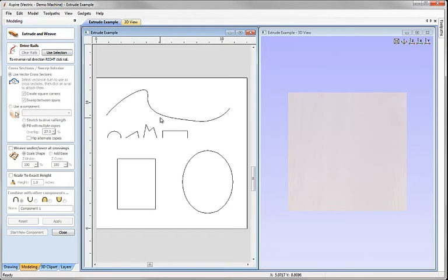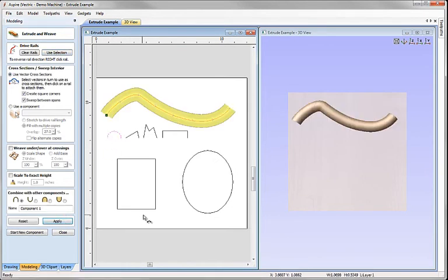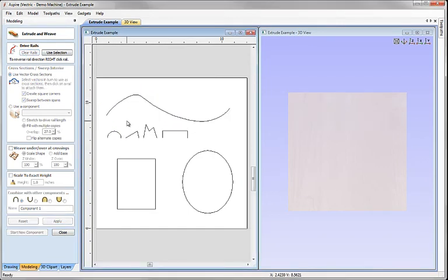And if I wanted to now, I could make changes to these again and use the node editing, and then come back in and reselect the curve, click on the Use Selection button, reselect my cross section and create a new shape. If I hit Clear Rails when I also have a component being created, then it will also eliminate the component as well as deselecting everything.